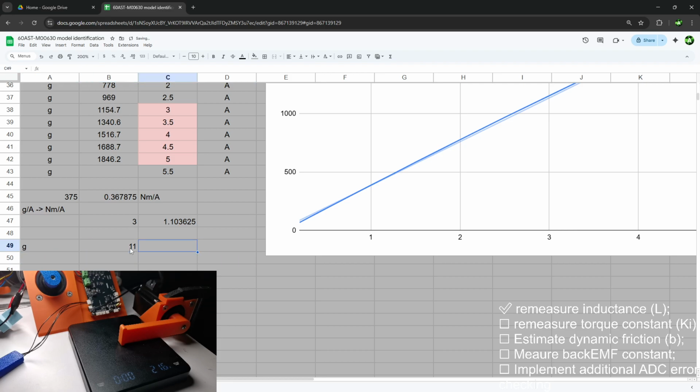And let's calculate our friction torque, just an assumption, because we will need it for dynamic frequency measurement. So we might as well calculate it. So we multiply this value by 981 to get our newtons. And we also multiply by 0.1, which is the length of our crank, so that we get the torque. Oh, and we divide by 1000 because we use grams and we need kilograms to use SI units. And this will give us Newton meters. Okay, looks actually quite reasonable.